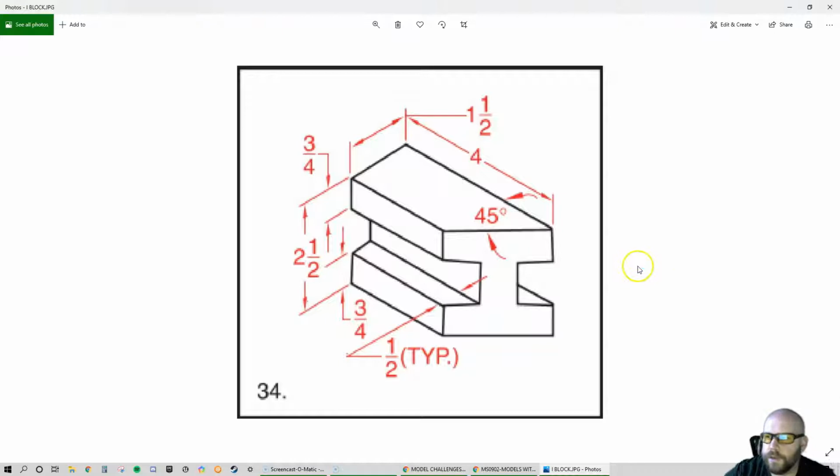Now there's a bunch of ways you could create this model. You could create a rectangle at the top, or maybe this slanted part of it, this top surface up here, and you could extrude it down, and then you could extrude this way to cut out these little sections in here. You could also extrude the front as a rectangle and then cut away this slant and cut away these 2 sections.